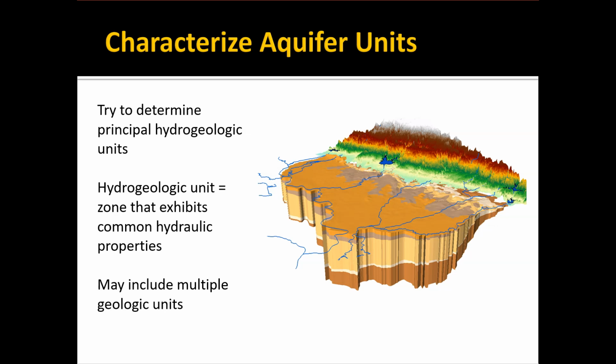This is a screenshot of a model that I was part of. I'll show a number of examples of this. This is near Sacramento, California. And the Z-scale here has been exaggerated. Up on the right there, it's part of the Sierra Nevada mountains, and there's Folsom Reservoir. And then the different colors represent the different hydrogeologic units that were used as part of this model. So again, part of your conceptual model is sketching out and deciding how you're going to lump things together in terms of the layering of the model. And that's an important process as well.